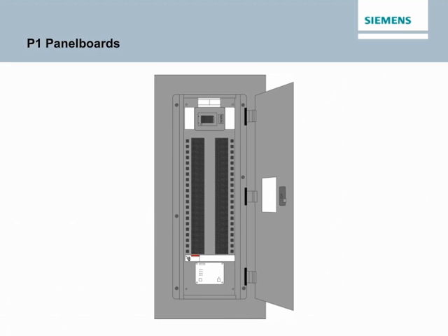Bonding provisions are shipped with each panel, suitable for use as service entrance equipment, assuming NEC compliance. 250 volt and 480Y/277 volt versions utilize identical boxes and fronts. The maximum number of circuits are 18, 30, 42, 54, or 66. The extended circuit options, the 54 or 66 circuits, often reduce project costs by elimination of the need for a second panel or the need to use a P2 or P3 panel instead of the P1.